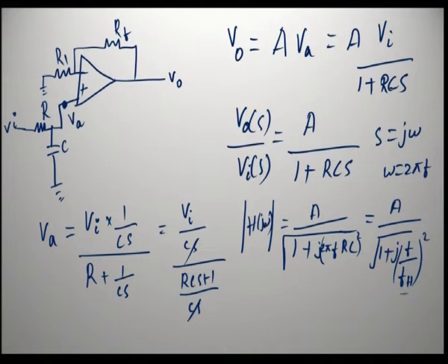Why is it f h? Because the low pass filter always has a higher cutoff frequency, because after this frequency all the signals will get attenuated. So, now we have to see the relationship between f and f h, and here what is f h? From the equation, this f h is the higher cutoff frequency, and it is decided by 1 by 2 pi RC, right.